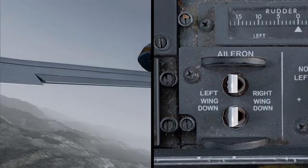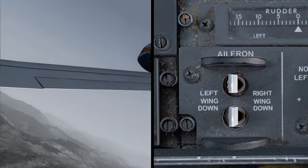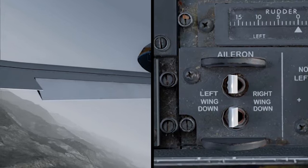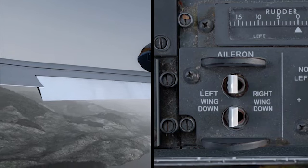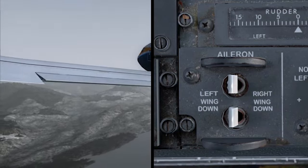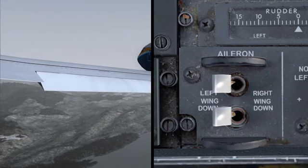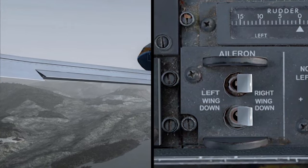When the aileron trim is in operation, an actuator moves the same aileron roller that we discussed before, causing springs to extend. This gives input to the power control units to move the ailerons, and the control wheels are also moved. Both aileron trim switches must be operated at the same time to supply power to the trim actuator.